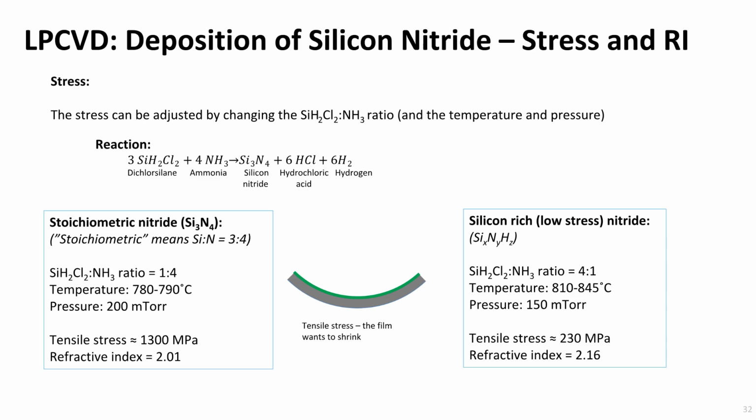Even though it would be possible to achieve zero-stress nitride films by increasing the amount of dichlorosilane, it is mostly not allowed at DTU Nanolab to reduce the contamination of furnace chamber and pump lines. In fact, furnace B2 LPCVD nitride 4 is solely dedicated to the deposition of stoichiometric nitride where low particle density often is a requirement. Standard recipes available at DTU Nanolab offer a balanced compromise between the stress in the deposited nitride film and the appearance of particles. Please be aware that the stoichiometry in the nitride film, meaning the proportion of components, can vary across the wafer and within the nitride film layer.